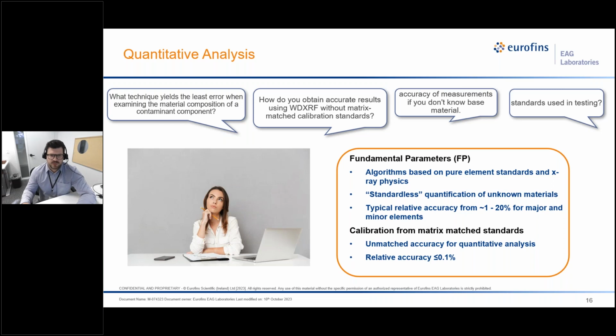These next questions we received revolve around quantitative analysis. Some questions include how do you obtain accurate results using WDXRF without having calibration standards, and what is the accuracy of measurements if you don't know the base material? So once a sample has been run by XRF, at the very least, we're always able to get you a qualitative analysis and know what surface or near surface elements are present. But in most instances, we're also able to get you quantitative results.